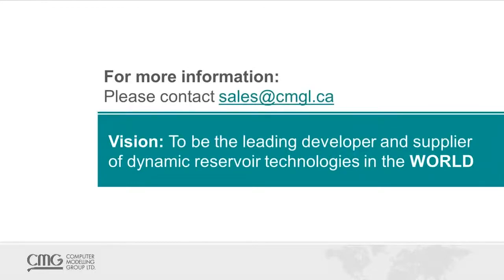So again, CMOST comes in handy in order to analyze the results in terms of relative sensitivities of different processes. The other question is from Bob, and the question is how the physical dispersion can affect the oil recovery in conventional CO2-EOR processes. So actually, as I mentioned before, the molecular diffusion has shown to be a main recovery mechanism in the fractured reservoirs, but still in the conventional carbon dioxide injection processes, we have seen a change in the oil recovery by the addition of the physical dispersions. So for example, if you add the diffusion or the mechanical dispersion into the model, then you will see a change in the oil recovery.